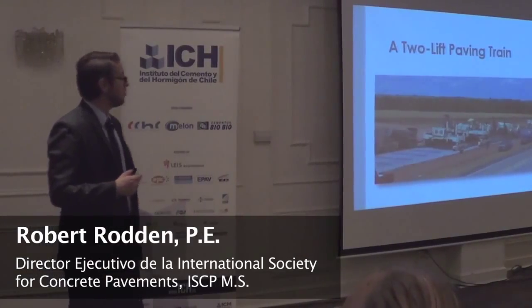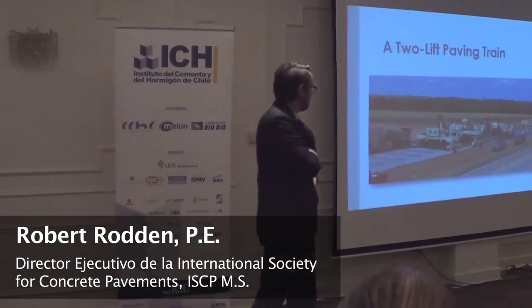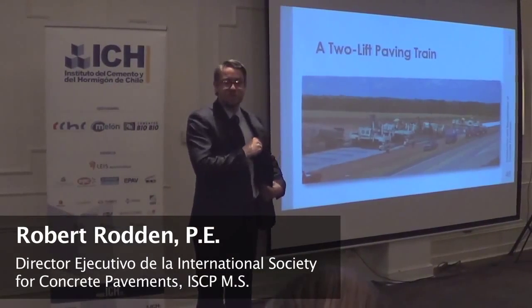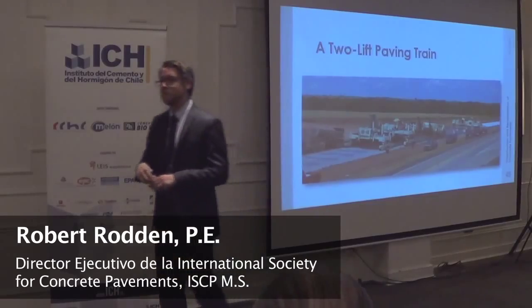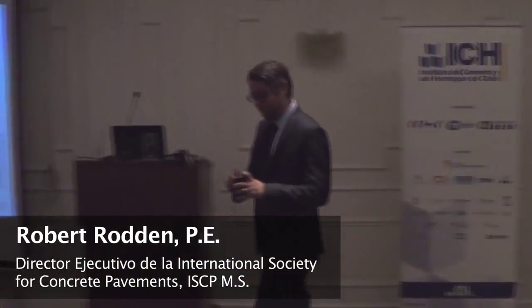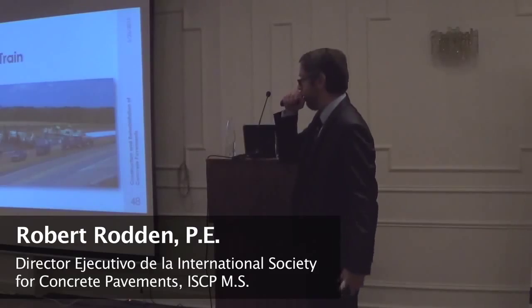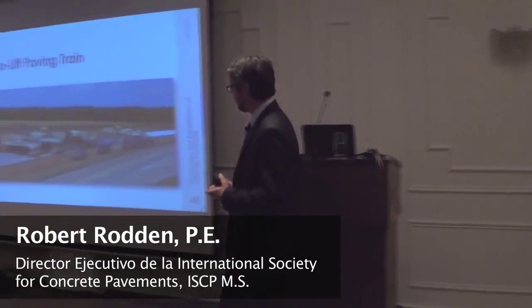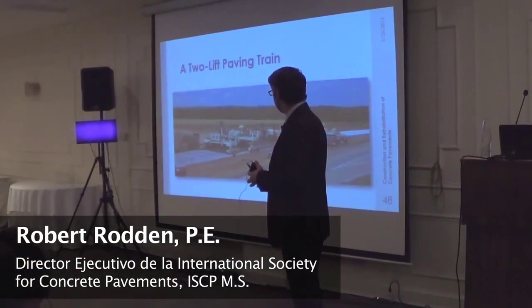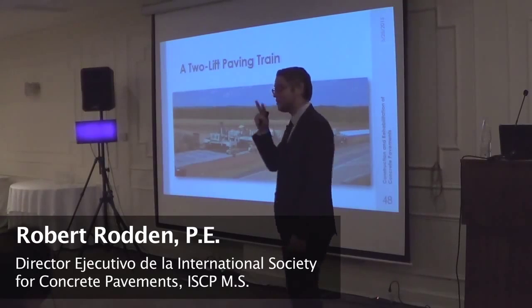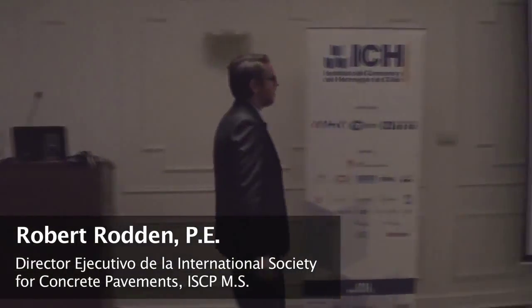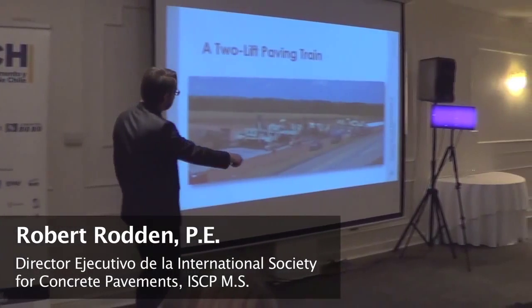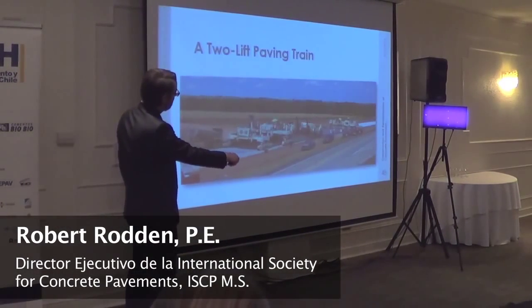In Europe, they'll use it to allow for an exposed aggregate surface. So for the same reason, they'll use the higher quality, finer gradation material at just the surface and not through the full thickness. This adds a lot of logistical problems, though, because you're supplying two different types of concrete to two different slip-form paving machines.